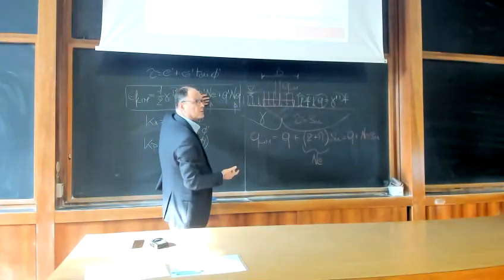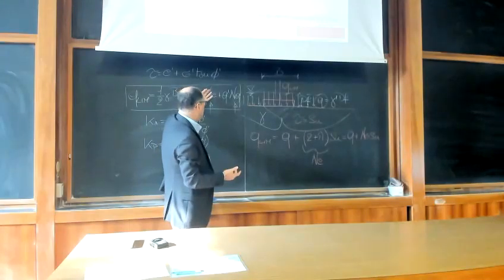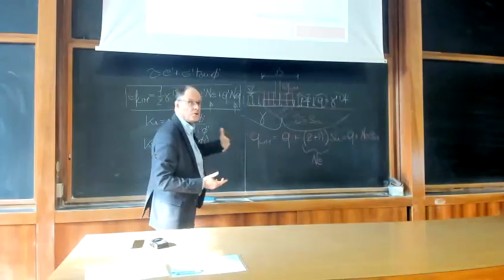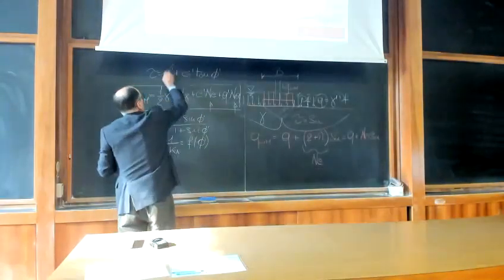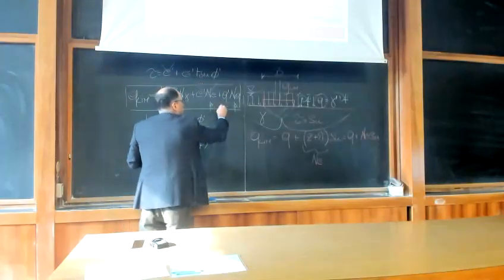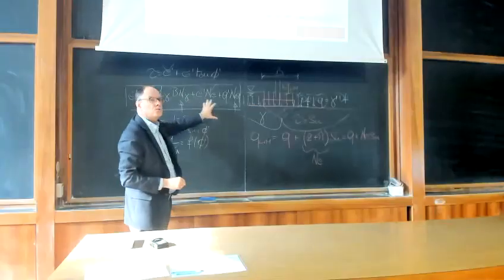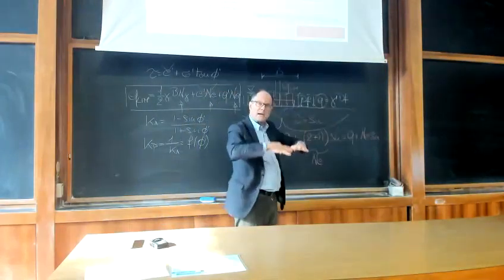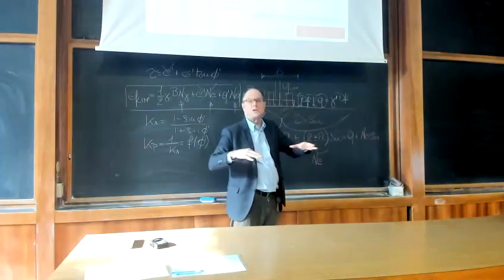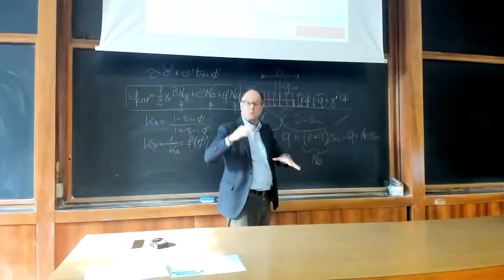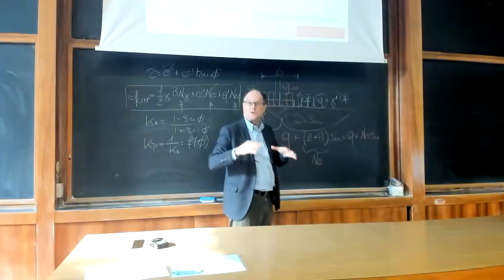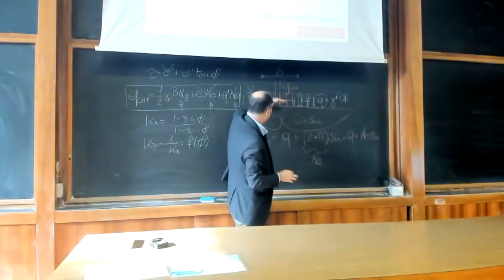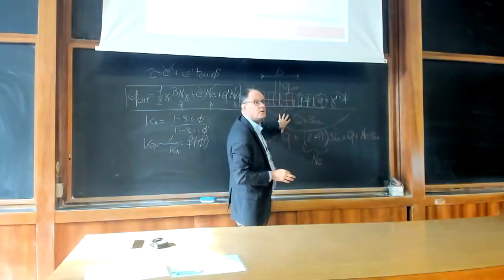The cohesion terms can exist or not. Because, for example, for a sand, which is a cohesionless material, typically this does not exist and this does not exist. So you are left only with two terms. And consider that you wanted to bed your footing on the ground surface, which is still possible even if not recommended because of the water content variations that we mentioned yesterday, but you can still put your footing on top of a cohesionless soil.